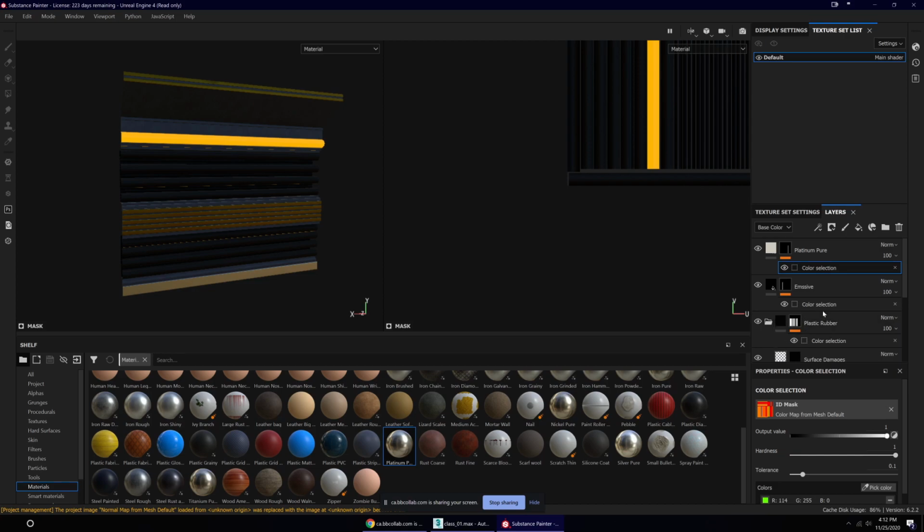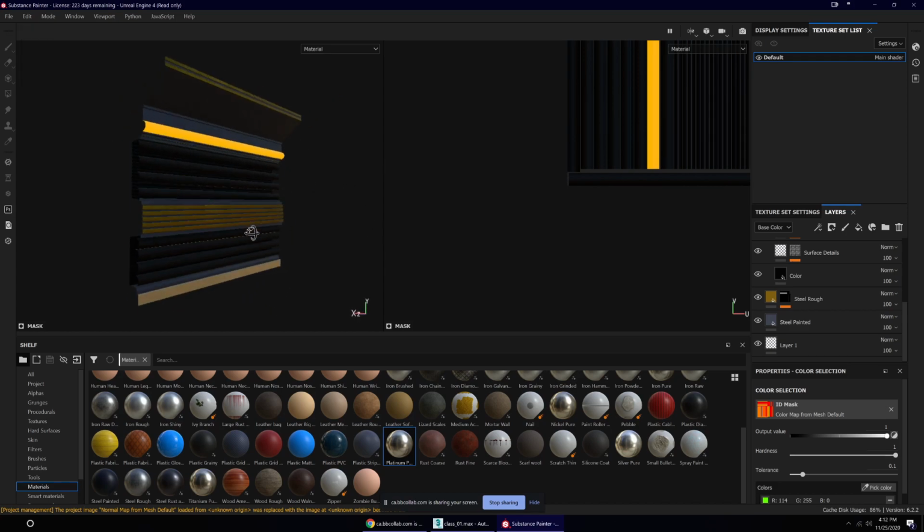Yeah, you would have to adjust the actual value inside of Unreal. Because the way it works in Unreal is that anything that is black is not emissive and will not glow at all, and it will receive shadow information. If something is set to the value of 1, which is usually the maximum value, it will not receive any shadows in Unreal. It won't glow, but it won't receive shadows. So it will give the illusion that it's glowing. But anything above 1 would increase the glow intensity, and that's essentially the key to make it look good. So what I'll do is that after we're done this, we'll put it inside of Unreal and take a look at what emissive would look like and how to set that up as a map.